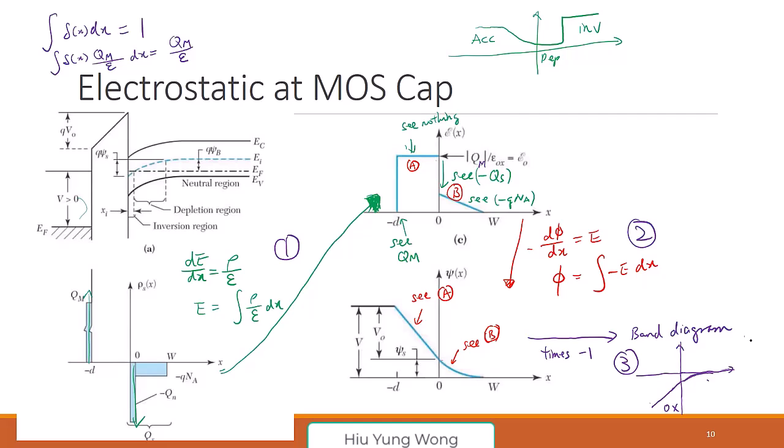So now it means your oxide. Just look at this one. This one tells you the potential. So in your oxide, you have the valence band and conduction band. So you just draw them in this way, right? Same slope going up. And then how about for the semiconductor? The potential is this shape. Again, you draw the valence band and conduction band, but they don't connect to each other because they have different band gaps.